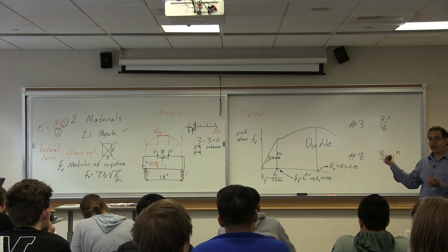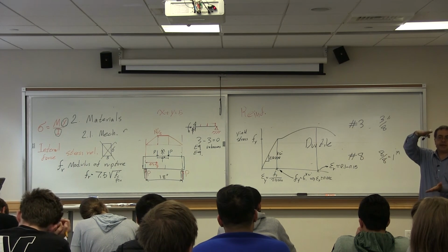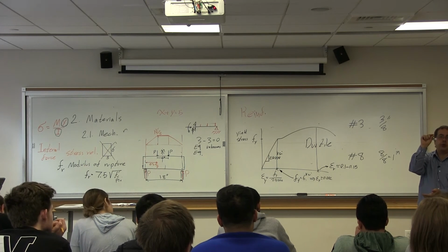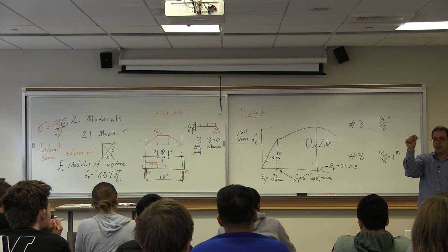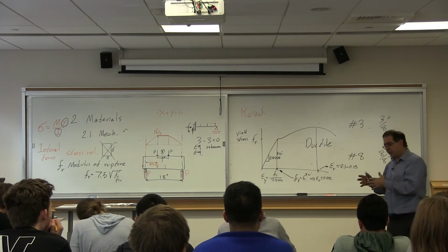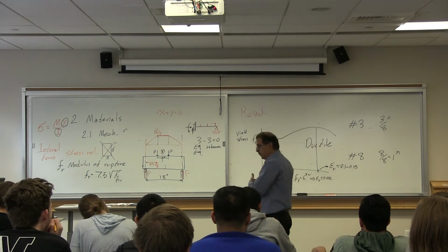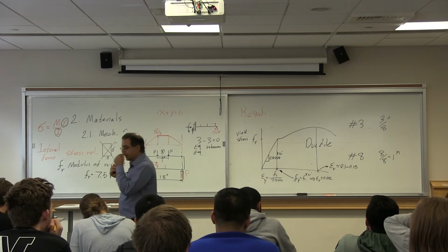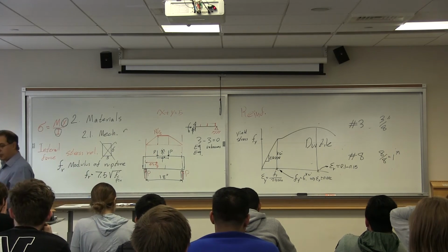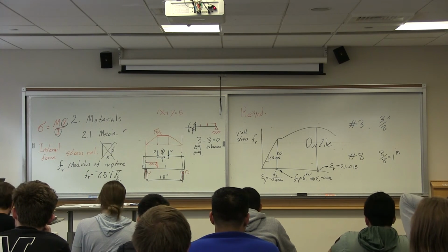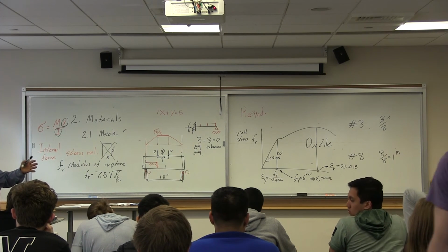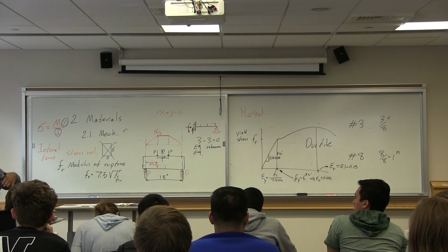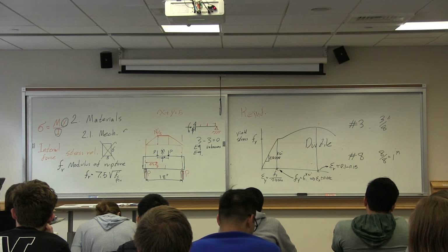But concrete, on the other hand, if you did the same test, it would move by 0.02 inches, and you cannot even notice. So concrete is brittle, rebar is ductile. The interesting science of reinforced concrete is that if you combine the two effectively, you can make a reinforced concrete that is very ductile.